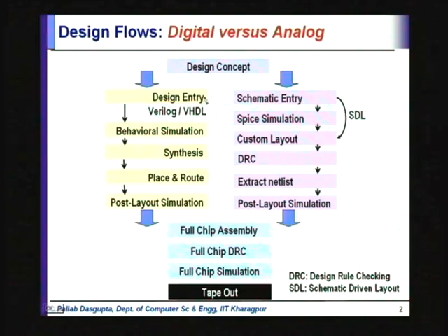Now, this design entry in the digital designs is typically in some language like Verilog or VHDL, and then to make sure that the entered design is correct and meets the original design intent, we do what is called behavioral simulation. So, the simulation is simulating that code that was written in Verilog or VHDL with appropriate tests and checking whether the output that the simulation produces matches with your expected output.